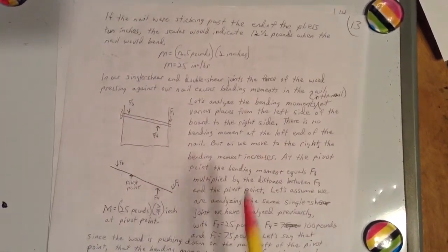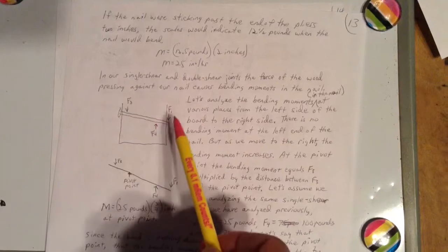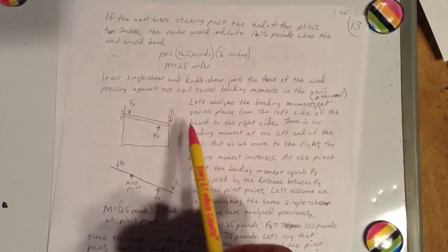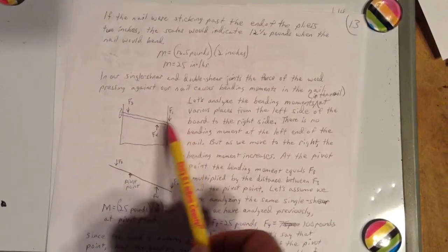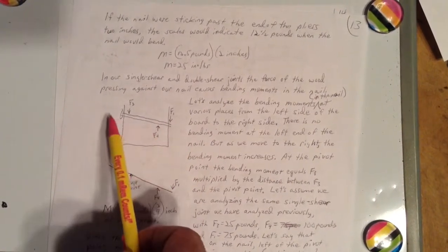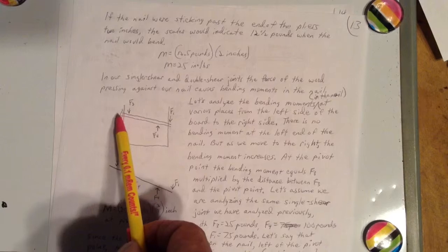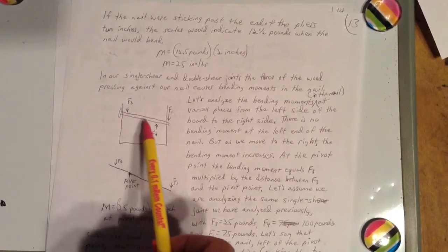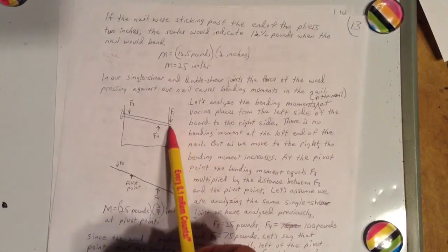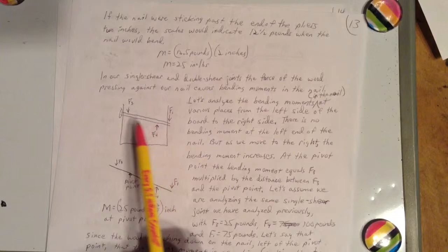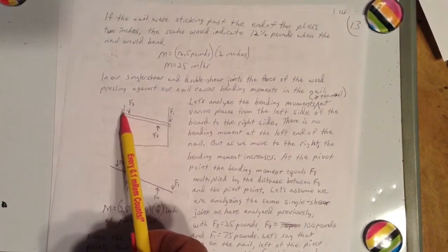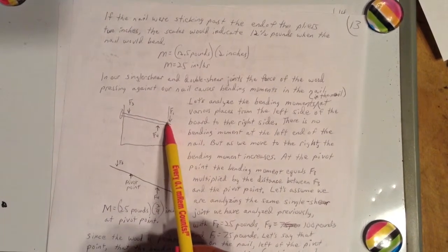Okay, we're going to look at, remember, this was our left board. There's another board over here. This is a single shear joint. We just didn't show the board on the right because the stresses in it are a mirror image of the stresses on the left. So all we really need to look at is one side. We're going to look at the bending moments along this nail from the head at the left edge of the board to the middle of the nail where the two boards meet, where it just has a shearing between the two. Okay, as we said earlier in part 4, there's no bending moment at this end of the nail, and there's no bending moment at this end of the nail.